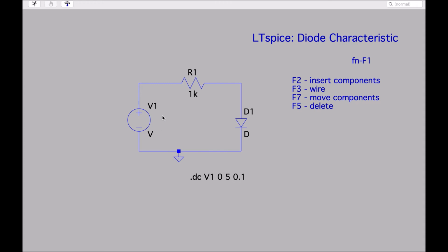The first one of which is when we hover over a component, we get this arrow here representing a current meter. We can plot current, and so we could choose to plot the currents in different circuit components. Because this is a series circuit, I would expect all of the currents to be the same, but if you've got a more complicated circuit, you can plot whichever current is relevant.